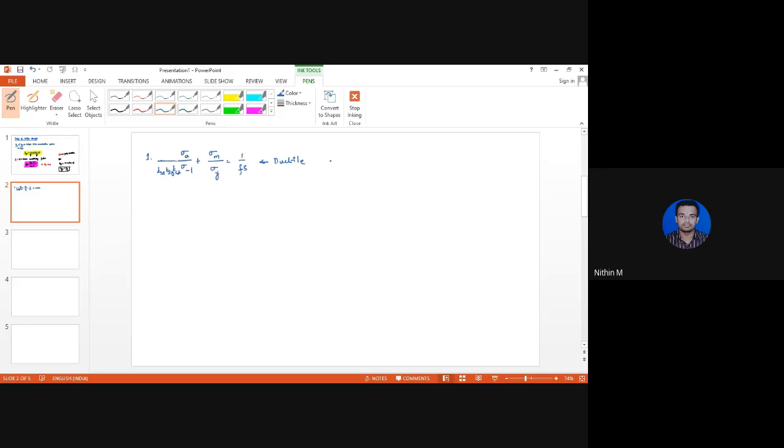Now, whenever there is stress concentration, we multiply the stress amplitude by Kf sigma to take care of the effect of the stress concentration factor. This is the modified Soderberg equation, or modified Soderberg criterion.